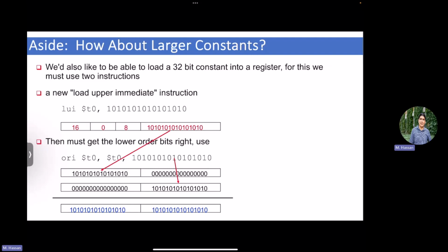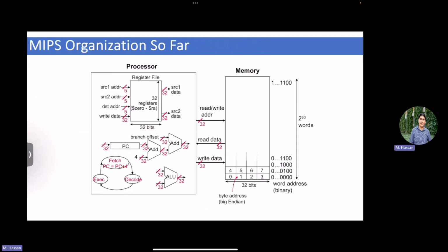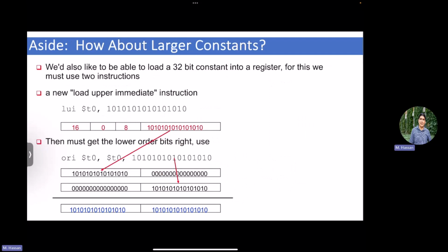So now you ended up with 2 registers. One has a value in the upper half, but the lower half is 0. And another one that would have a lower half value, but the upper half is 0. If you want basically the 2 values, what you do, you OR them, right? Because simply these are 0. If you want this value and this value in the upper and the lower, if you do a simple OR operation, it's simply done. Okay, are we good so far?